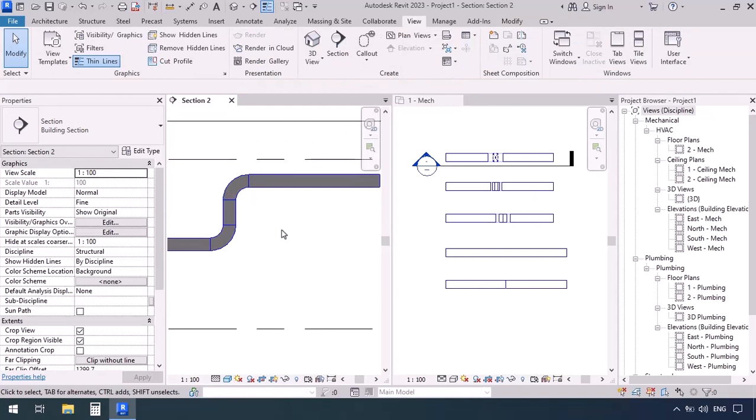So as we change the elevation in our plan, and depending on the elevation that changes, we might end up seeing so many different shapes. As in, we might get 90-degree elbows, or 45-degree angles, or an elbow with a different angle. And we even see that this distance was so small that it couldn't even apply a fitting. It only distorted the duct, or it created an offset by itself. So it really depends on your elevation.